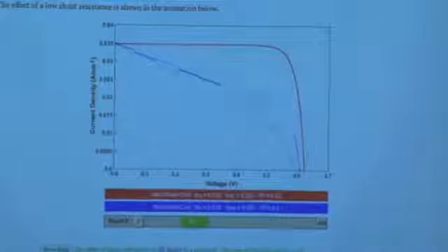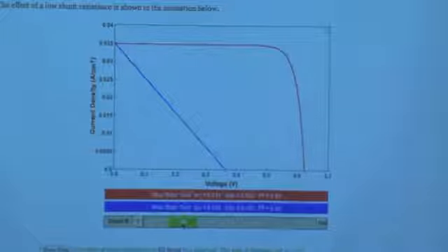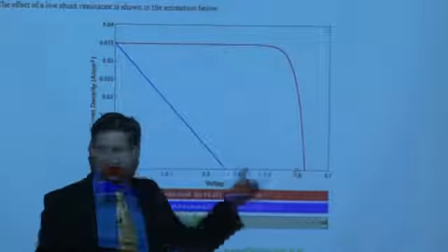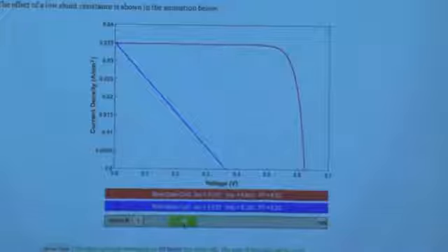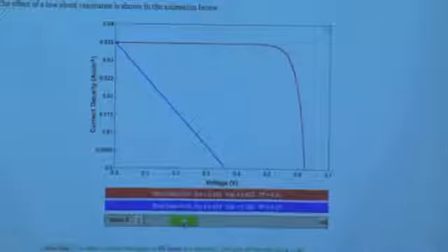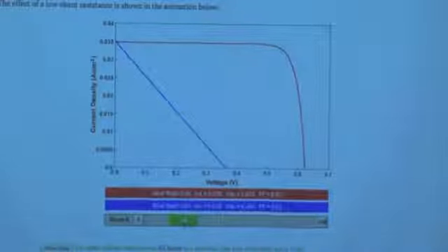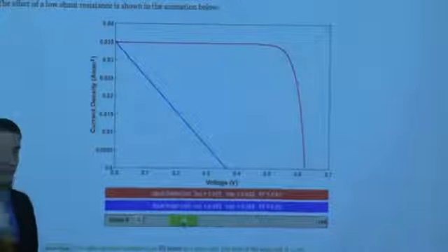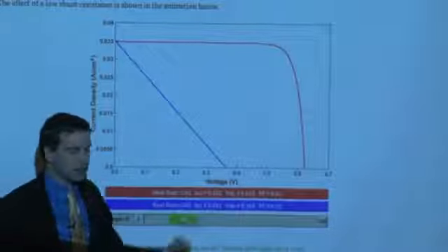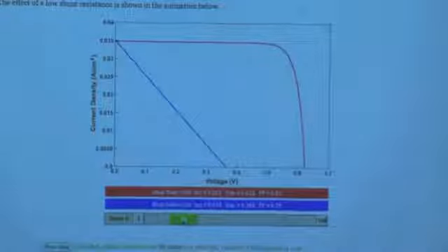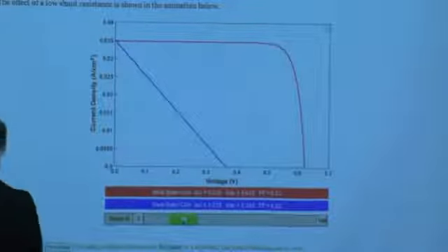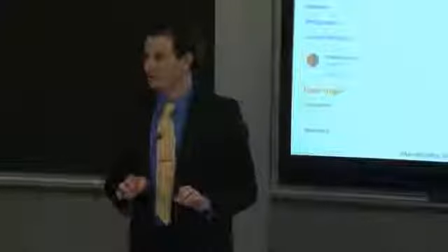And at some point, we drop the shunt resistance so much that now the voltage across our solar cell is even suffering, because there's not enough separation of charge sustained to make that voltage large, because the current is being shunted back inside the device. And again, we have what appears to be a very linear IV curve. So you can see when you measure your solar cell and you test it and you get a linear IV curve instead of that nice exponential, you have to do a little bit of troubleshooting to figure out what exactly is going on. OK.